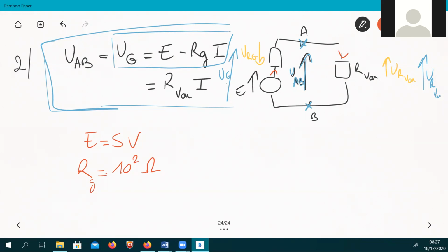Could you just explain? I know it's just using the graph, but I think I'm getting the wrong answers for R, because do we have to do something to convert it into ohms? Yeah, again, you have the same problem since your current on the x-axis is in milliamp. It's not amp. To get ohm, you need volts and amp, but here you have volts and milliamp. So you have a 10 minus 3 factor. Yeah, okay.